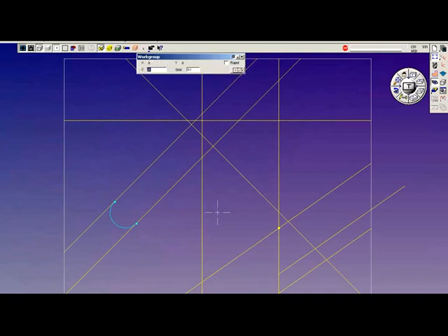Line, mouse line, anchor it, move it to a given location, and you can see where you're drawing by using this register right up here, X and Y. Lets you pull it, and you can draw a perfect rectangle by watching the values, or you can get into a more free form look.